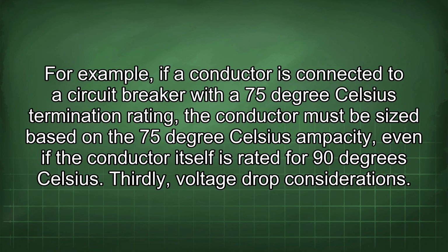For example, if a conductor is connected to a circuit breaker with a 75 degrees Celsius termination rating, the conductor must be sized based on the 75 degrees Celsius ampacity, even if the conductor itself is rated for 90 degrees Celsius. Thirdly, voltage drop considerations.